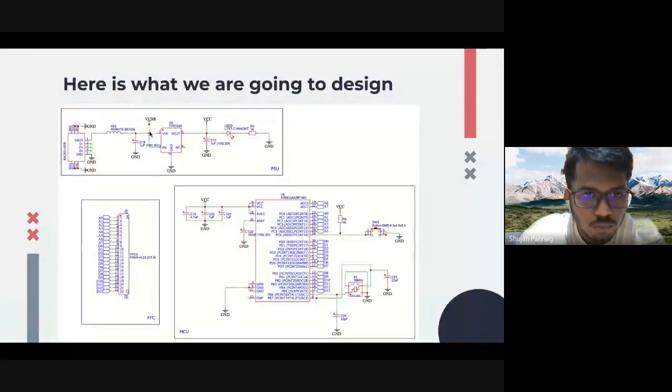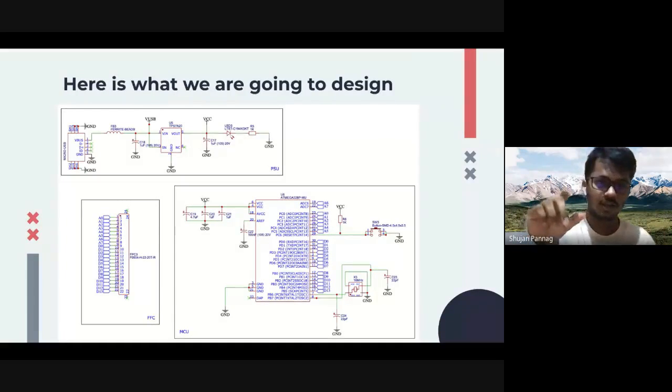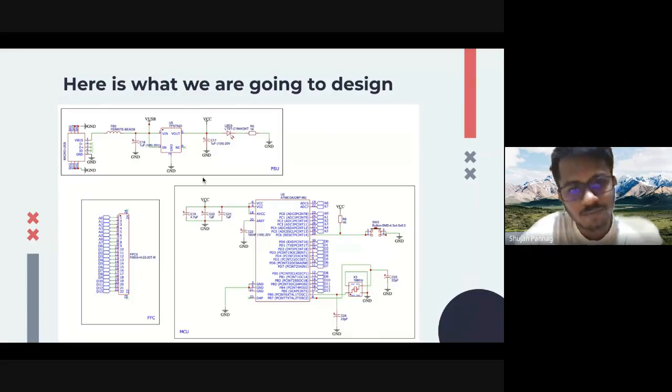And then I've put two flags, like ground flags, and everywhere here. When you connect it, you see it in your schematic, then in your PCB, all of these will be connected internally. The reason we'll be using this is because it separates it, and we don't need to connect the ground everywhere, which would be really messy and would probably ruin the aesthetics. So that's why we'll be using these flags. Anywhere you refer to VCC, here or here, these are all the same point on the circuit, which will be interlinked. Okay, so that's what those flags are.